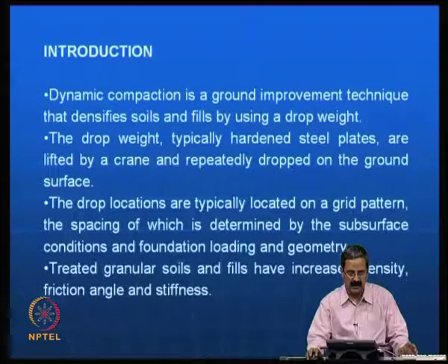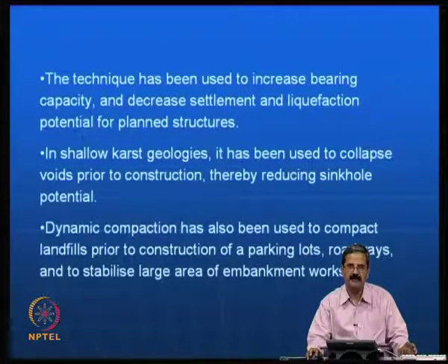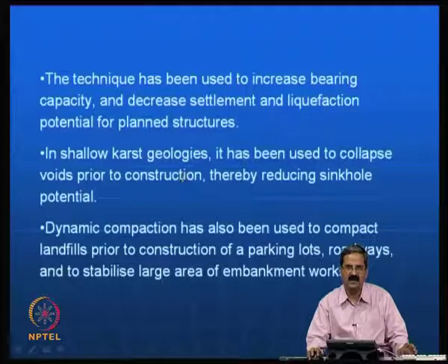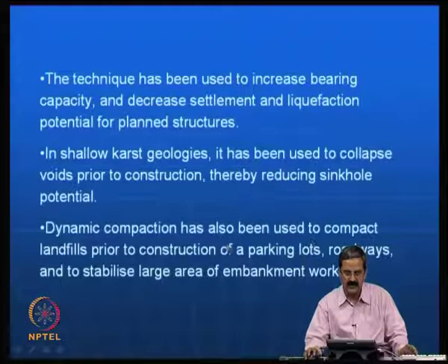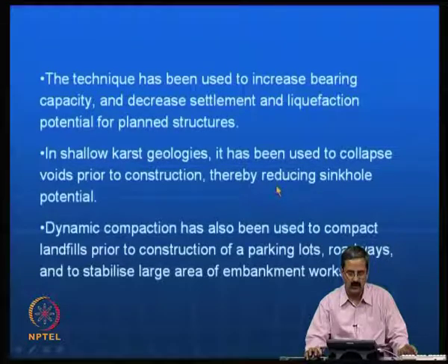Normally, treating granular soils and fills has always resulted in increased density, friction angles and stiffness. We will see how this can happen. As I just mentioned, this technique has been used to increase bearing capacity and decrease settlements and liquefaction potential for plant structures. In fact, this is one of the very important applications. In shallow karst geologies where the soil has a tendency to collapse, it actually reduces the voids prior to construction, so that the sinkhole formation potential is reduced.